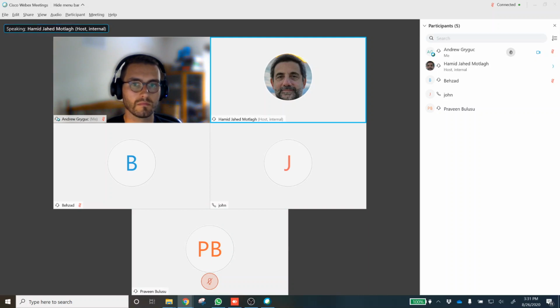And in terms of properties, you want just the regular elongation, ultimate value, and things like that. Yeah. For strength, we would need both the with and without case hardening, and for fatigue, we only need the case hardened. For fatigue, only the case hardened. I see. Okay. Because you expect the crack to always initiate on the surface.